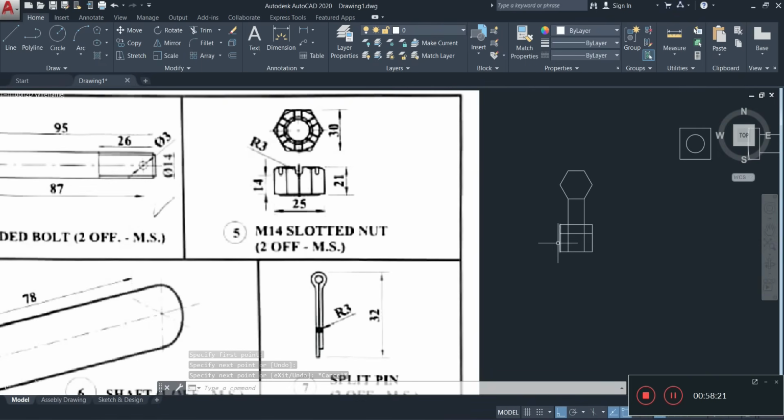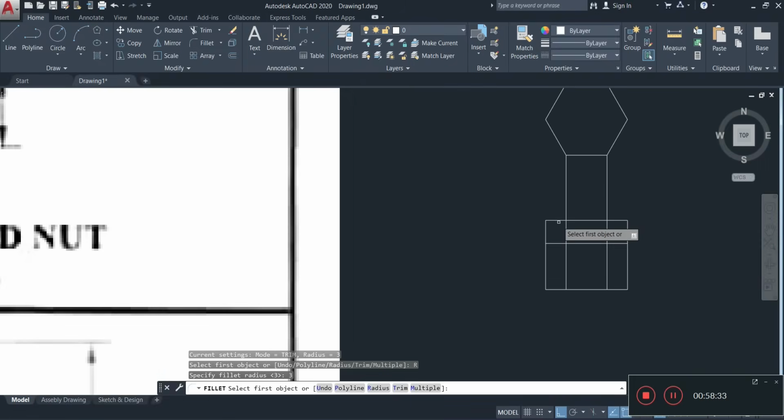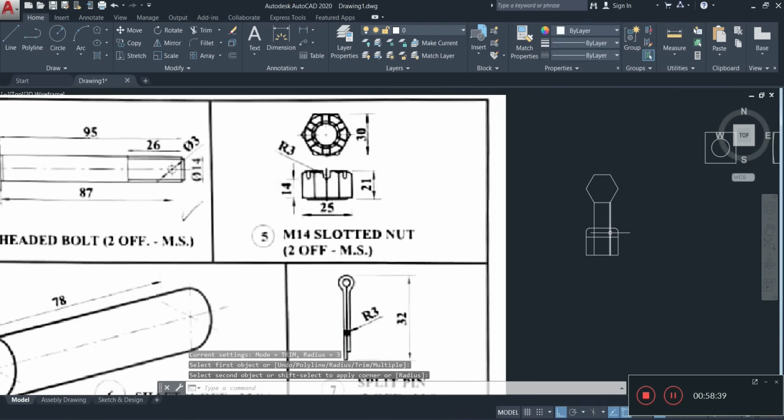So let me just see if we can sort that out. On the edges, there are going to be some curves as well. Remember, the curves are actually 3mm. So let's sort that out. So let's fillet here and here, here and here. Let's see that all is well.